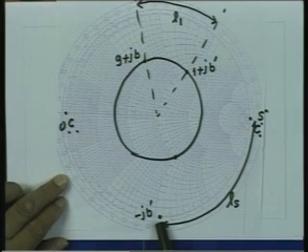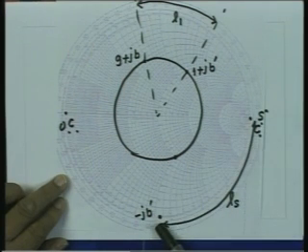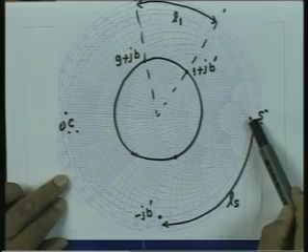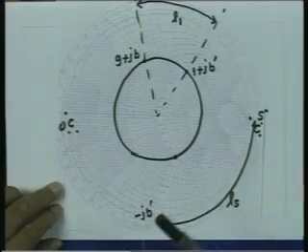go to the outermost point on the Smith chart on that circle, and find the length of the stub from that susceptance to the short circuit point, which is the rightmost point on the Smith chart. So, by doing this simple exercise, we can find the location and the length of the stub. A similar exercise can be done if you are having impedances, and if the stub is connected in series, you use the Smith chart as the impedance Smith chart, and beyond that point the exercise is exactly identical.